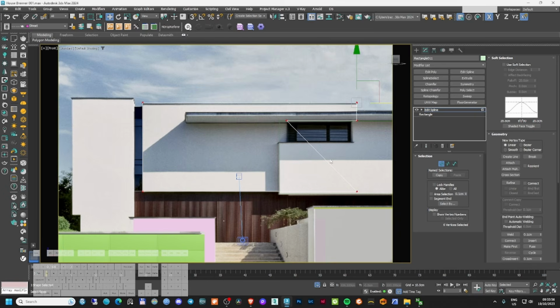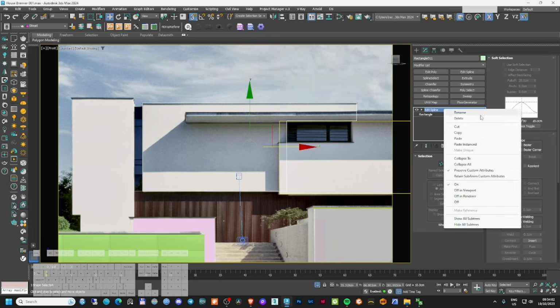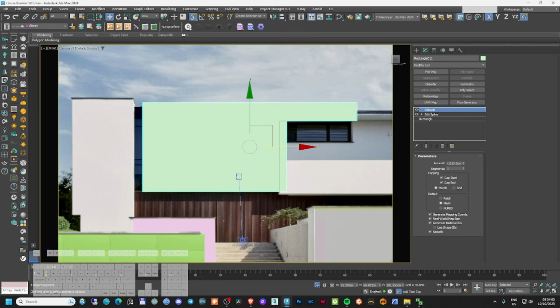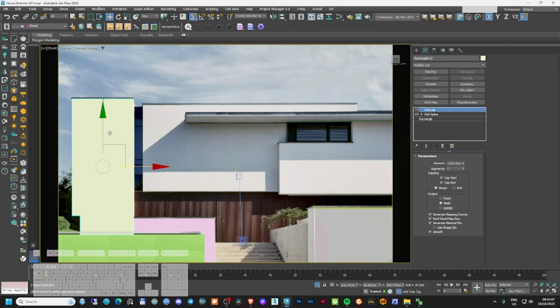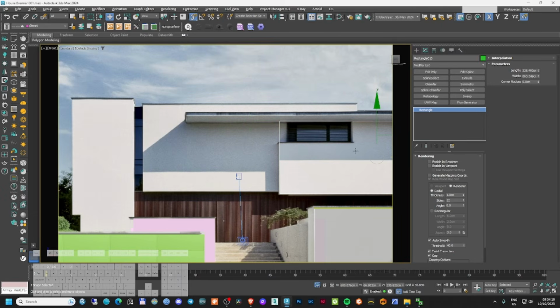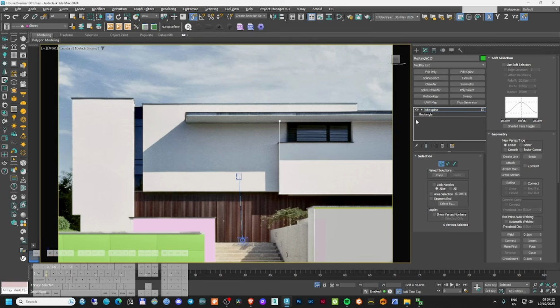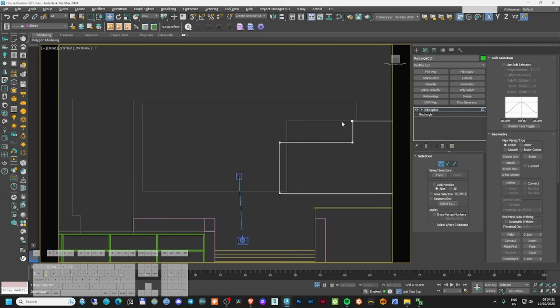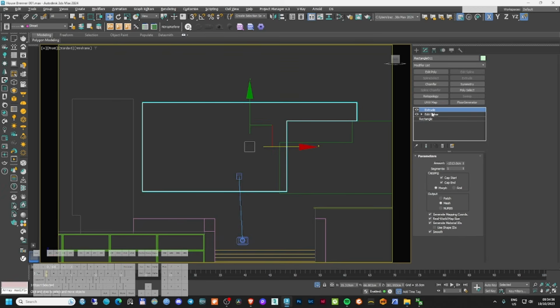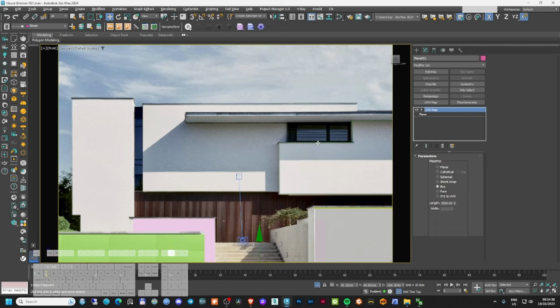Control all corner, and this is gonna go here, and I will just apply also an extrude to all of this. I will use an Alt X just to see some stuff behind, and then here I will do exactly the same using the refine. And yeah, I'll apply also an extrude to this.